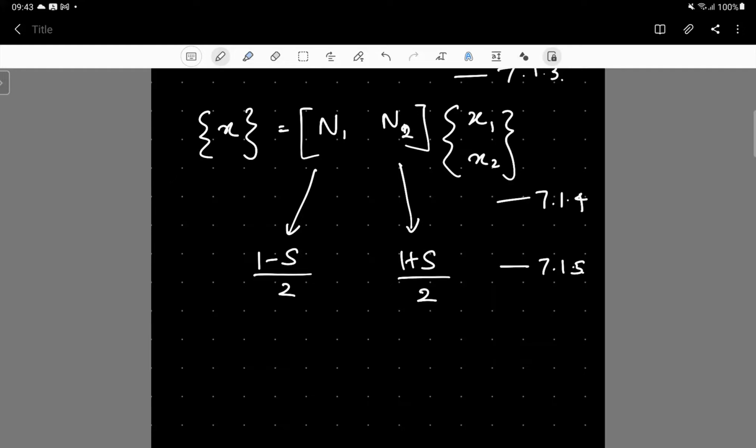x, which is when it is plotted over the element, meaning the shape function would be 1 at node number 1, and it would be 0 at all the other nodes, meaning at node 2 it would be 0. Similarly, n2, the shape function, when it is plotted over the length of the element, would be 1 at node number 2, and of course 0 at node number 1. And when you add these two shape functions at any point within the domain, it would be equal to 1. So these properties corresponding to the shape functions are also relevant in this case.